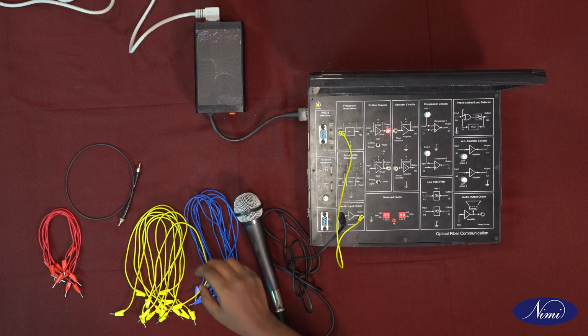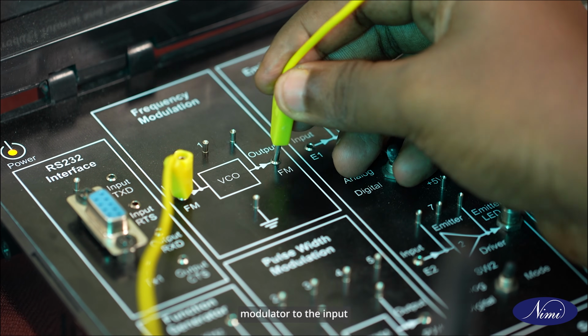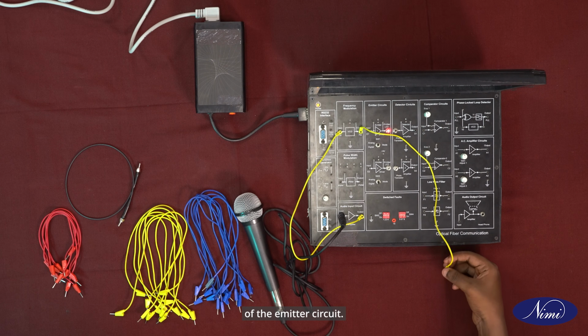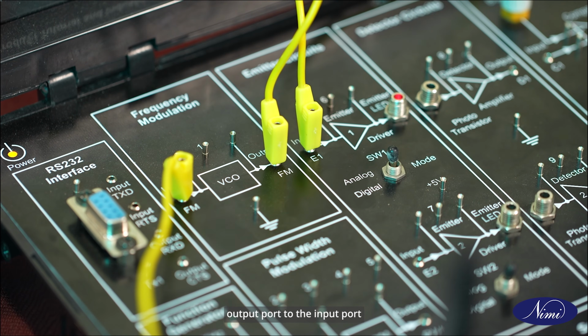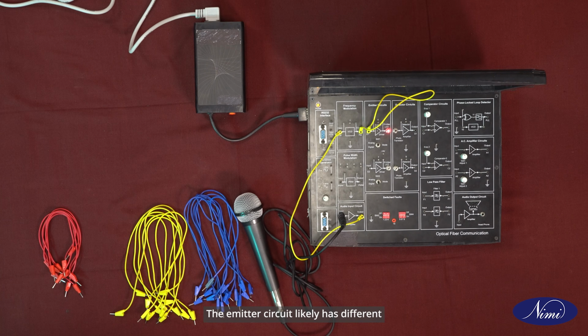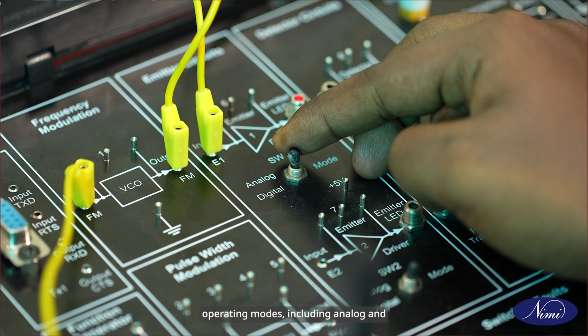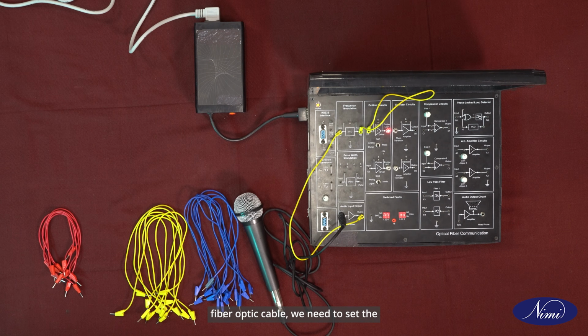Prepare for transmission. Now connect the output of the frequency modulator to the input of the emitter circuit. Use a suitable cable to connect this output port to the input port of the emitter circuit. The emitter circuit likely has different operating modes, including analog and digital modes. For transmission through fiber optic cable, we need to set the emitter circuit to digital mode.